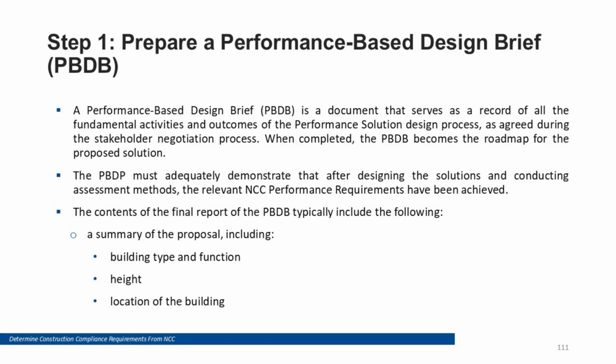Prepare a performance-based design brief, PBDB. A PBDB documents what is being proposed and how compliance will be proven. It typically includes building description and objectives, relevant performance requirements, the agreed assessment process and acceptance criteria, supporting evidence required and reporting format. This becomes the roadmap for the performance solution process.